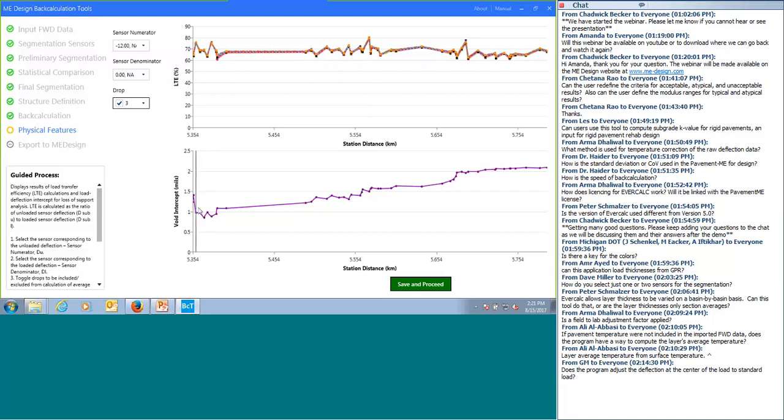The other is the void interpretation, which is typically used for rigid pavements. We've also included it for flexible pavements. The one interesting item is that below about a 2, as has been established, you typically have good support or no loss of support. If you get greater than 2, you have what's been defined as some kind of loss of support, typically for rigid pavements.